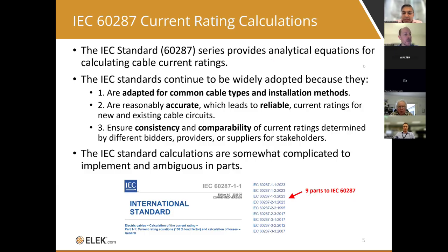But IEC 60287 calculations are generally a little bit simpler. Simple methods, for example, cable crossings, like we needed to extend those calculations. Many of the calculations had to be extended because they deal with one or two circuits only at the max. For example, transients can do only one circuit at a time. Cable crossings can do only a cable and a steam pipe at a time. So there are many restrictions and limitations. They're relatively quite simple, but the fundamentals are really important and still good.